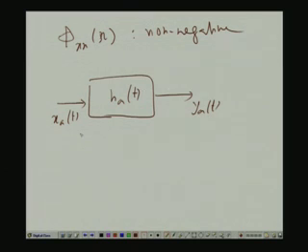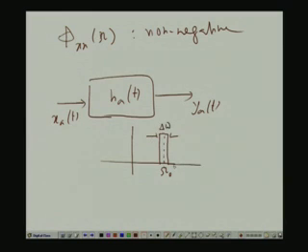Okay. Now, I design the system h a t such that it is just a band pass filter, very narrow pass band. I am not showing it to be that narrow here, but actually very narrow, infinitesimally small bandwidth, center frequency is some omega naught. Capital omega is my notation for analog frequency, that is radian per second. So, center frequency is omega naught and this bandwidth is say delta omega. Okay, this is my H A j omega. Obviously, H A t in this case is complex, because as you can see H A j omega is just one sided. I do not have a similar thing on the left hand side, and therefore, if you take the Fourier transform, it will be complex valued. So, H A t is complex valued here, but I do not care. Okay.